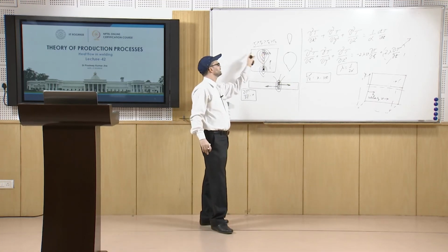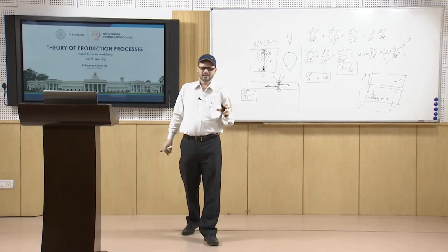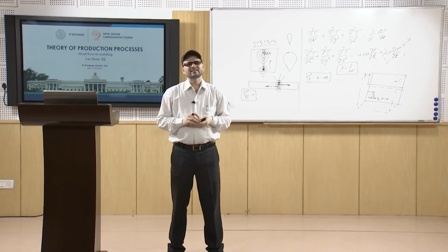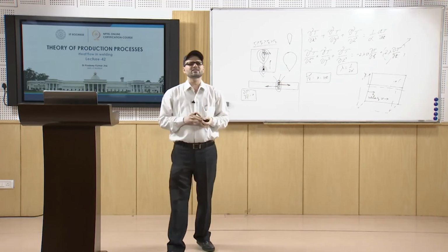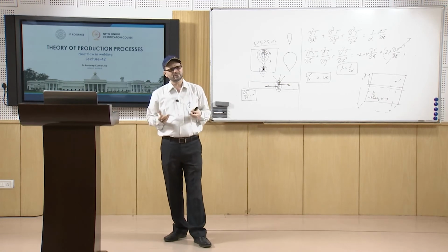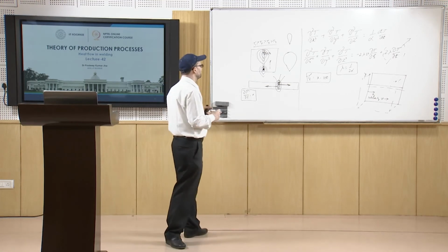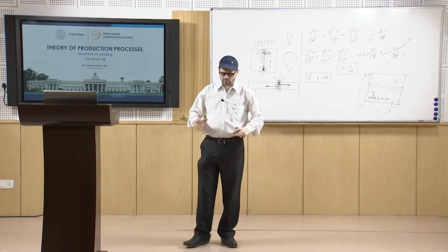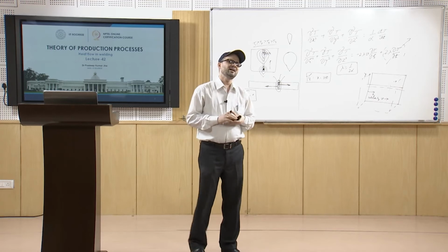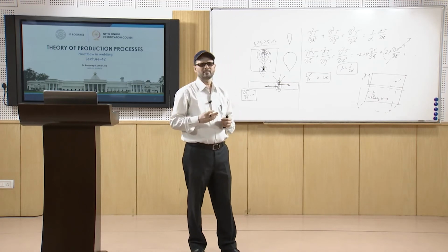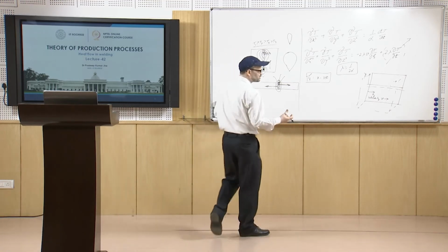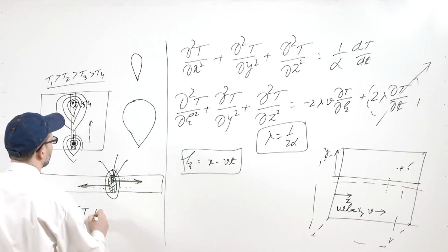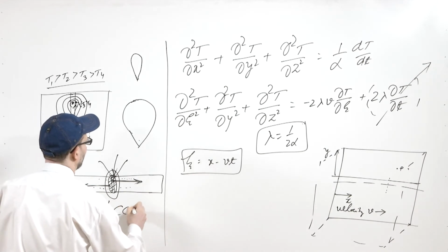Now, from these isotherms you can have the cooling rate determination. So, once you know these isotherms at different points, then cooling rate can be found, and once you know the cooling rate, then from there you can predict the microstructure and mechanical properties, because you know that you have different types of curves. You know that when there is transformation, then depending upon the cooling rate you will have the transformation products, like you have TTT or CCT diagrams which are available.